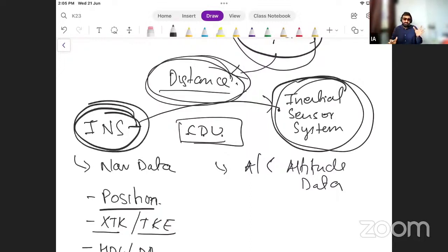The navigation system or INS will have the sensor unit, and it will have the control panel also, right? The whole system will have it, while the sensor unit will only have the accelerometers and the computers. They are the sensors. The input and the visible screen will be the CDU. Okay, control and display unit, we call it generally. So we control things from this and we also get display of the information. So not computer display unit, it's just control and display unit. I'll be showing you pictures right now.